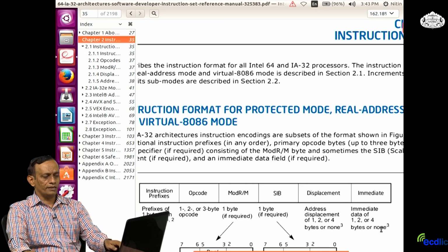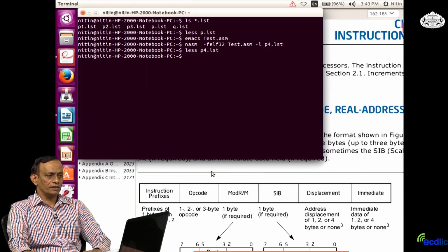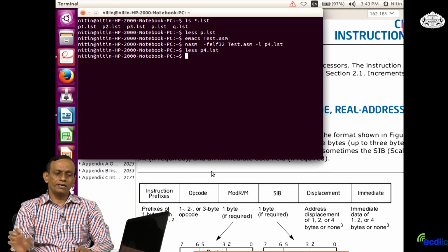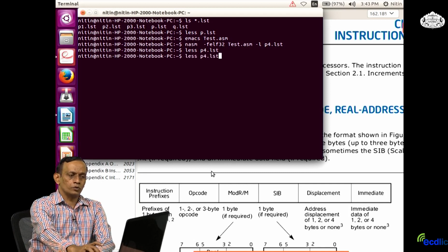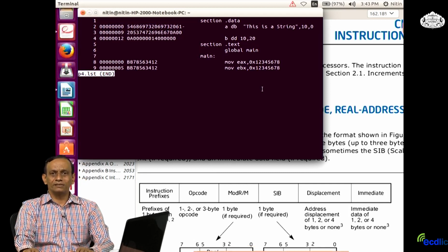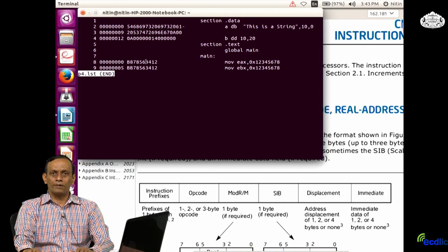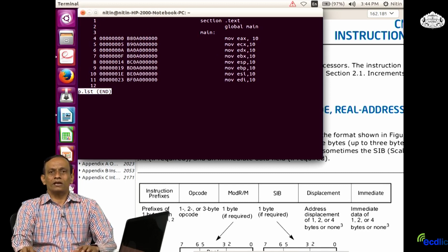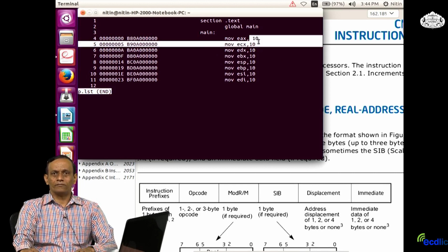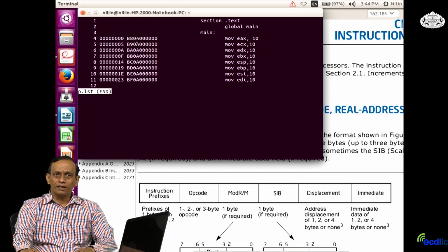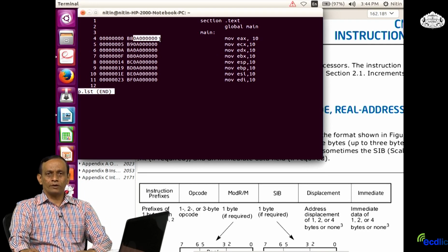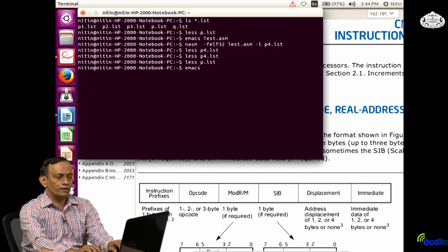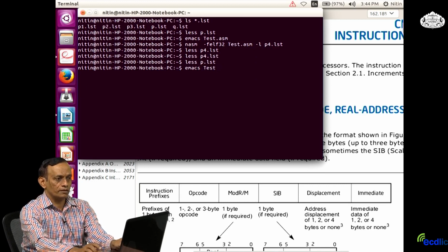Now one important thing that we will see in today's session: when we talked about the move instruction, we saw that it took completely 4 bytes. To store this data, it would be translated into 4 bytes. In the earlier example, we gave only the value 10, which can fit into a byte, but it ultimately took 4 bytes to represent it because of the little endian notation.